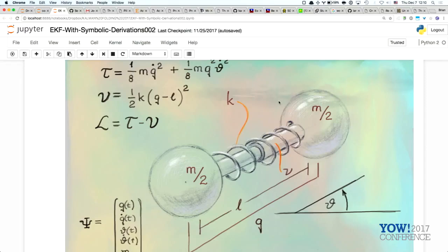I have seen gaming engines and physics engines for games that are built entirely out of this dashpot. I spent years working on tires for racing car simulations. A tire is one of the most complicated objects in existence, and this is why racing simulators came out only decades after flight simulators. Flying is easy compared to twisting a tire on the tarmac. Amazingly enough, you can build a model of a tire out of a truss of dashpots, and you can fool a Formula One driver with it. I did it when I was working on Forza at Microsoft.